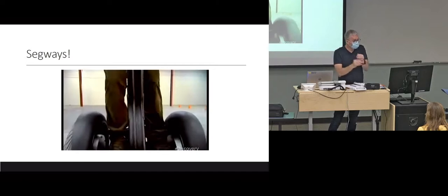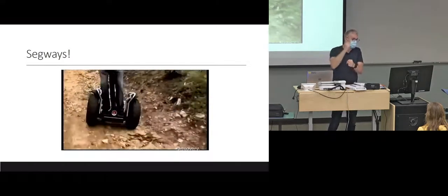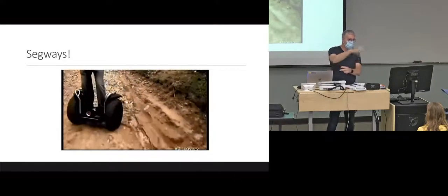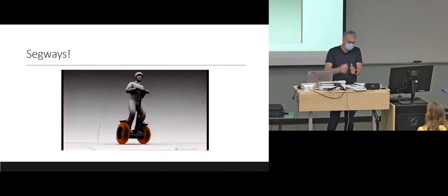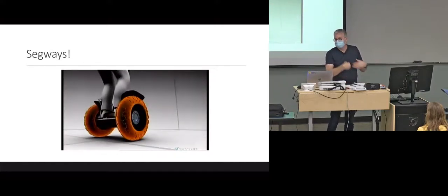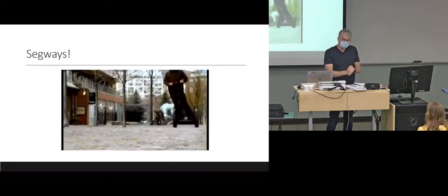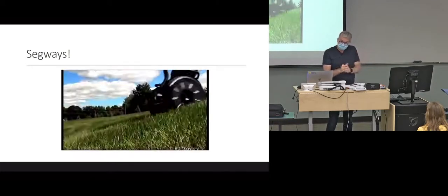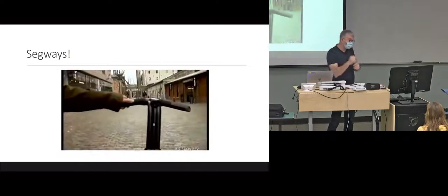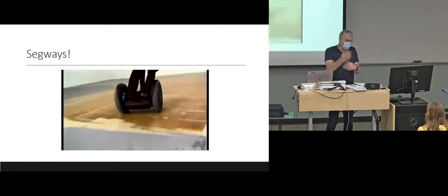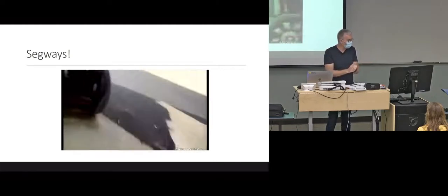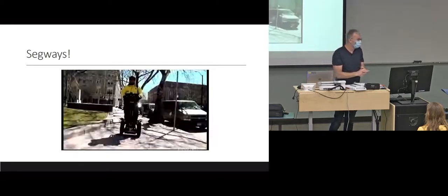So model predictive control is predicting the future using your model based upon hypothetical control actions. You then optimize over all possible controls that'll get me from point A to point B. And that's how model predictive control works. It's model predictive to see the future, but you're going to compute a whole sequence, apply one of those controls, see what it really did, recompute your control, and keep going. So it's a little bit weird. It's all explained in the handout, and you're going to have a blast, okay? That's all I can say.